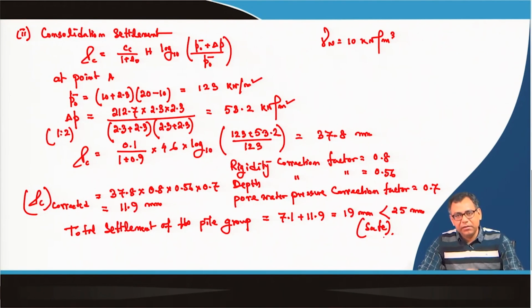In a similar way, by using the pile bearing capacity equations for sand, you can determine the bearing capacity of the pile group in sand also, and the settlement of the pile group in sand also. I have already discussed the settlement of a raft or shallow foundation resting on sandy soil. So, the same equations you can use, because I have used a similar type of equation here for settlement calculation of the pile group or the raft for clay.